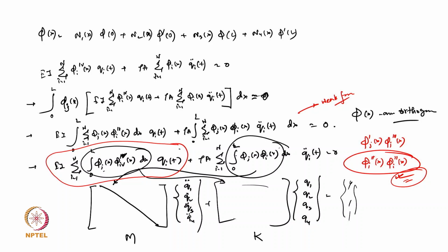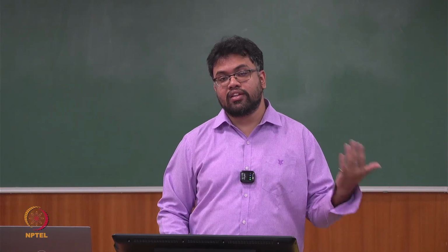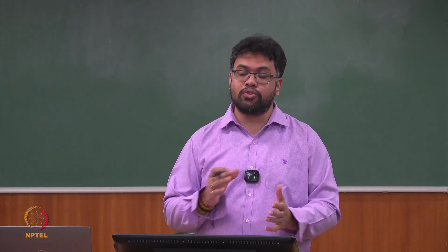But here the difference from the standard finite element is that we are using shape functions which are continuous throughout, and which express the field in a much better manner. We don't need to do any discretization. Here these terms are not discretized in space; they are the modal superposition actually. They are the different modes, so we are coupling all those modes together to get the solution. This way this can be thought of, and we can get the matrices.